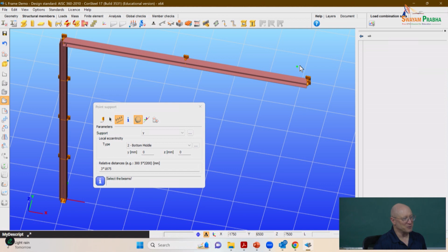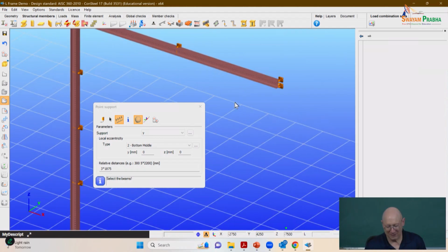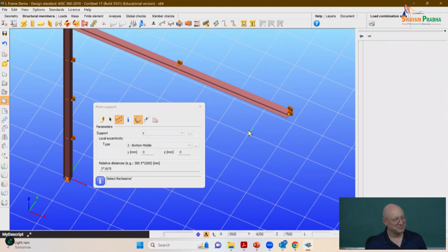So it has the smarts, so that if I told it to use 4 elements, and I say, oh, but I want some other boundary conditions, it's going to say, oh, okay, I'm going to have to use some more. Irrespective of whether it's a node or not. Correct. That's good because your structural stability doesn't dictate the finite element efficiency. Correct. And generally, it's the other way. As a rule, I think they have heuristics where if you leave it on automatic, they automatically put in a mesh that usually works pretty good, but then you can control it manually.